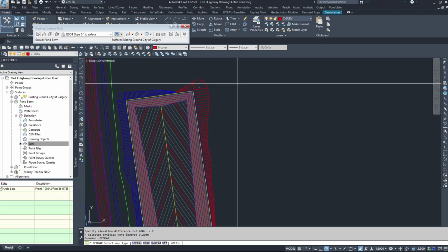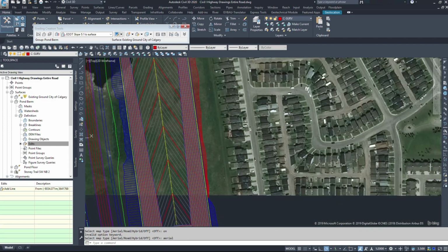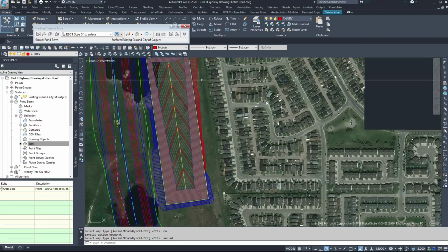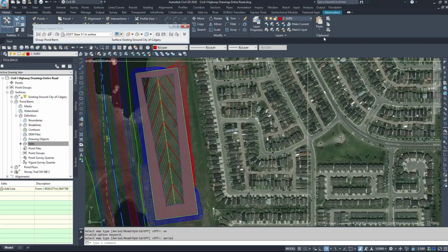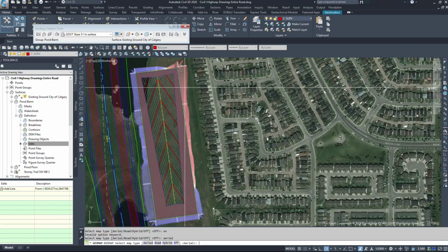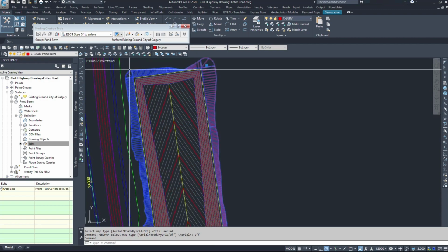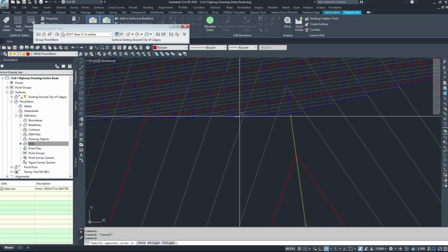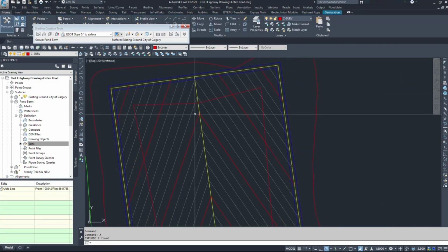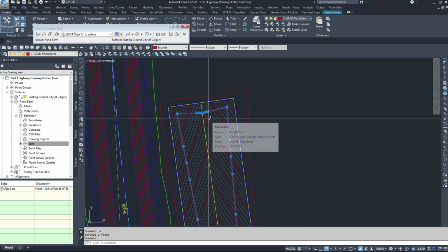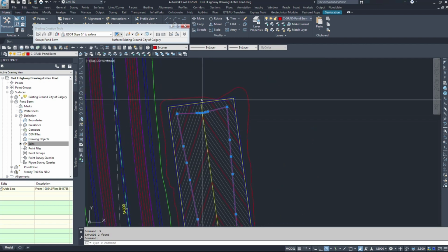And finally, geomap on, aerial, sorry, to make sure I haven't interfered with any of these houses. If you want to leave the geomap on, go for it. I'm purely turning it off because it slows Civil 3D down when I'm trying to design. So geomap off. And then we are going to take our two grading objects, so these two outside feature lines, and explode them. I want to get grading objects out of my file. I don't want to leave them around after I have my design done. They are one of the most unstable objects in Civil 3D, and they can cause crashing.